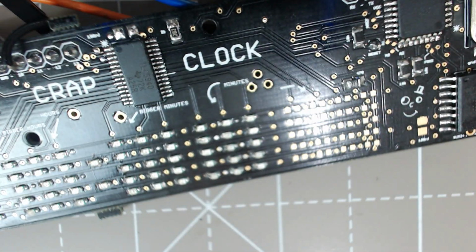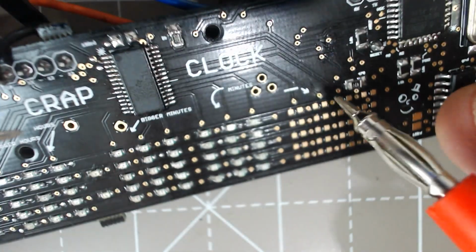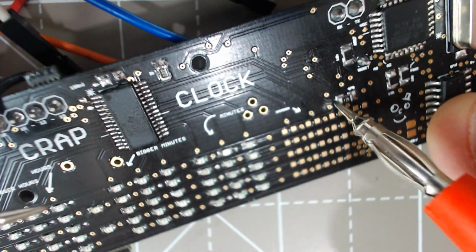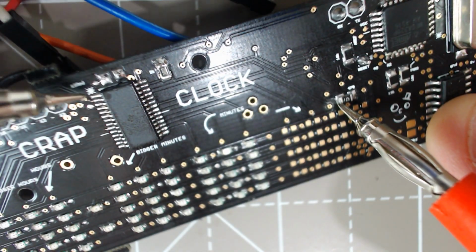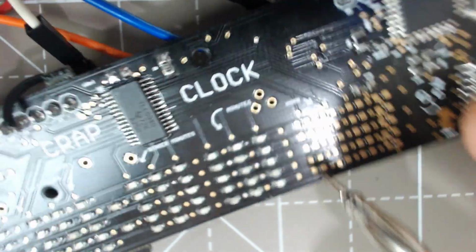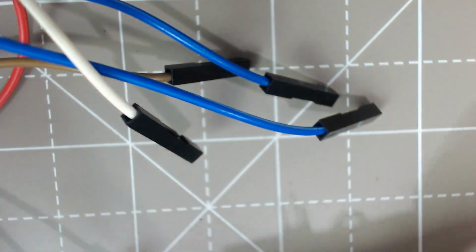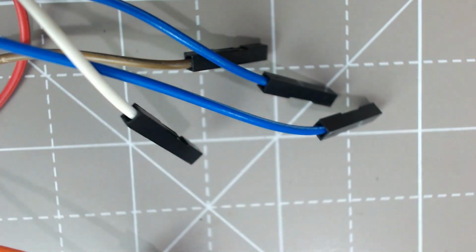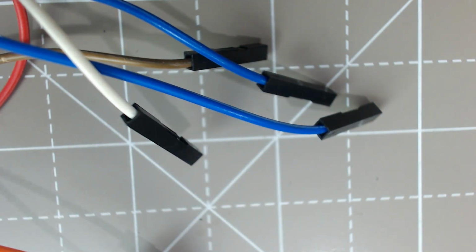So let's just check it's connected, and we'll just use continuity mode to do that. And we'll check it's connected to one of the pins of the TLC 5940, and that should be up here. In fact, let me just look at the board because I'll be able to see it properly. So the last row is connected to roughly the middle pin.